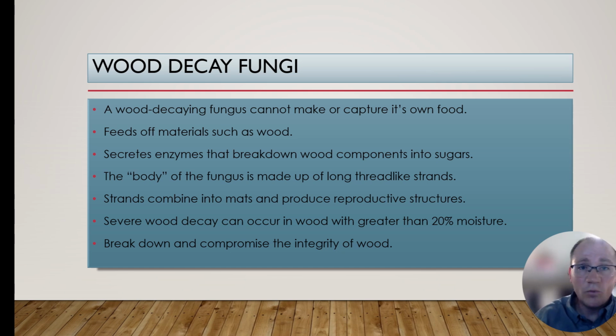My advice is when it comes to structural issues, I wouldn't stay too much on that with people because most of us are not structural engineers and we really need to think about what we say to people. If we do think there's a major structural issue, we might suggest that they hire a structural engineer. But I do want you to know that with severe wood decay, it's usually going to be greater than 20% moisture. So as you're going through crawl spaces, and we're going to even talk about moisture meters, the amount of moisture and percentage is going to be a big deal in telling you what you're running across and what you can do about it.